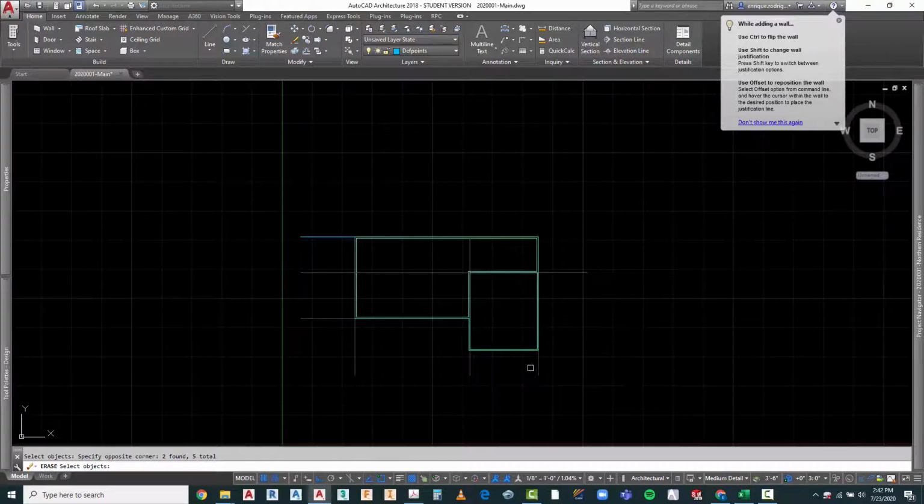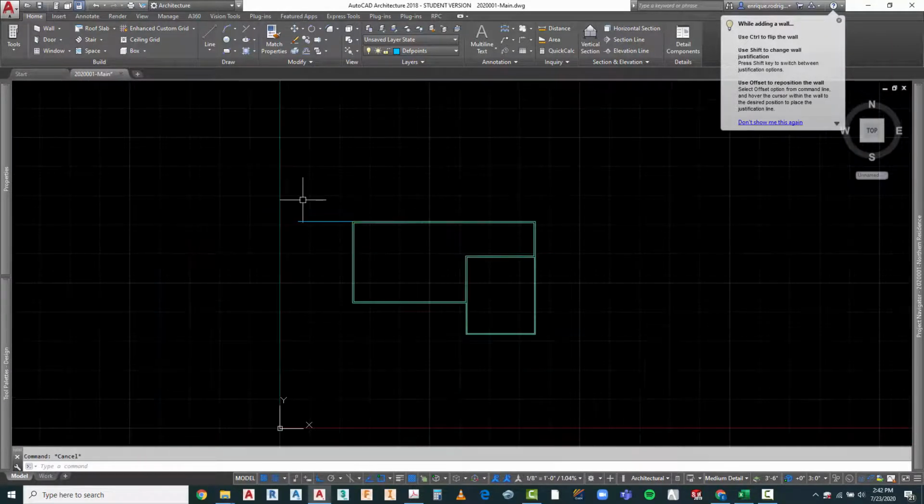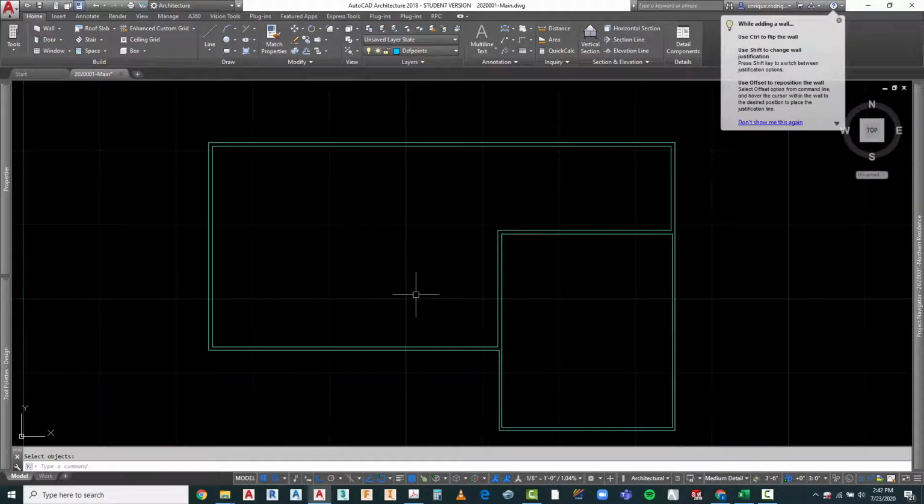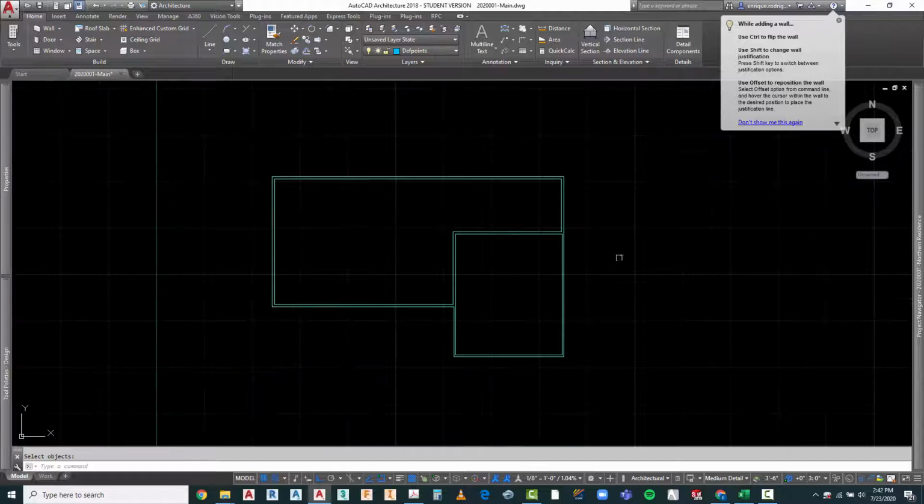To me, having too many lines gets a little cluttered, and if the drawing's cluttered, my mind tends to be a little bit cluttered. One thing also is, in the markups, either the engineer or the architect would probably tell you how high these walls have to be. You sort of have to have an idea of what the structure is going to be, how big the floor structure is going to be, so that you determine what the stud height or the wall height is.